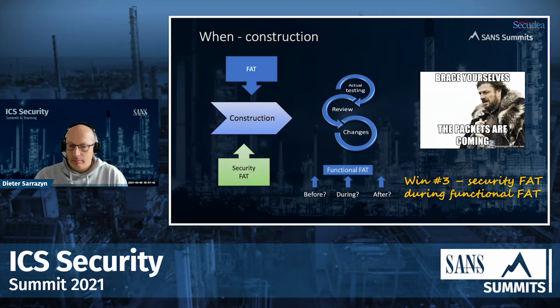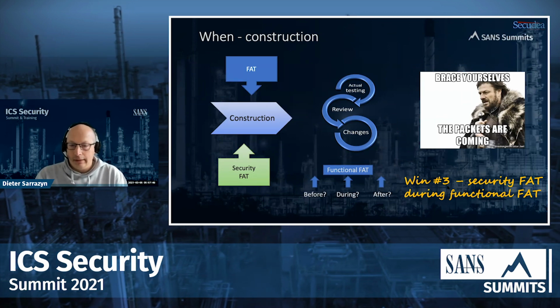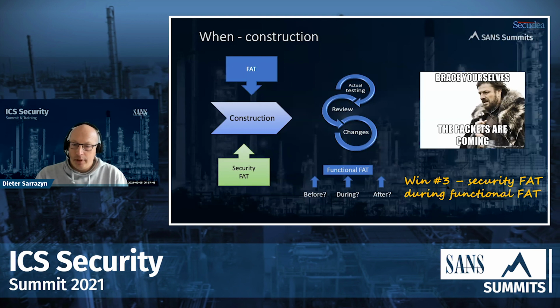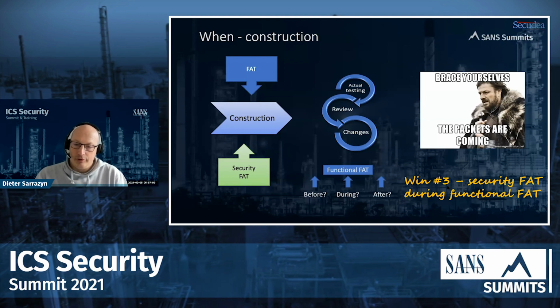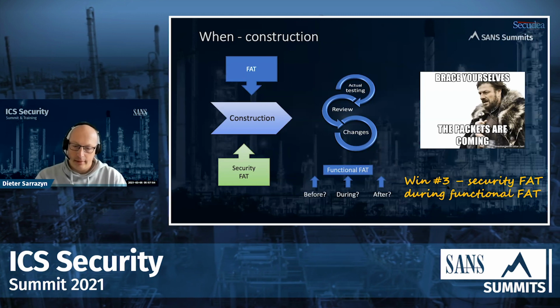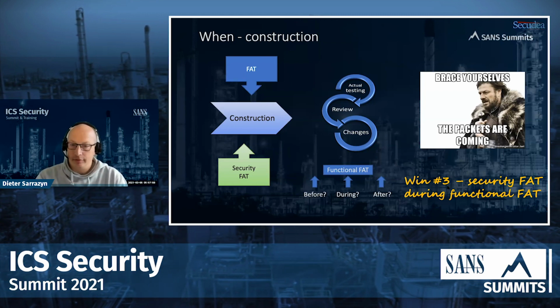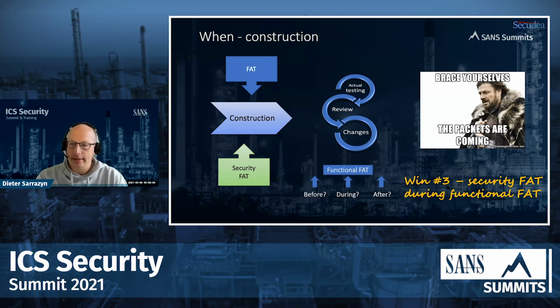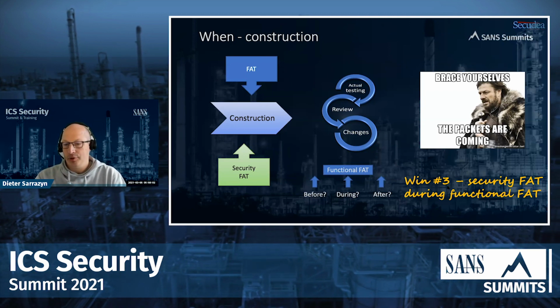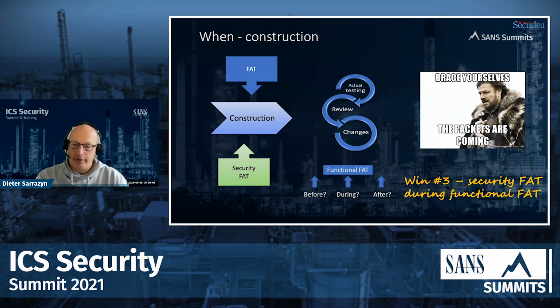So there's debate: do you do it before, during, or after functional FAT? In my opinion, there's a win here if you do security FAT testing during a functional FAT test. Why? I'll tell you why. When the operators or the engineers are actually doing the functional FAT testing, they are really working with the system. And at the same time you do security FAT testing, they will see the behavior of their new